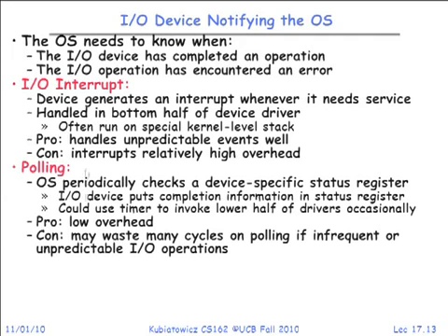What's the downside of polling? It's on my slide, but what does it mean? Yeah, the problem is if you've got an unpredictable device, you're wasting all this time. Are you done yet? Are you done yet? And so interrupts are great for unpredictable behavior because you're not wasting a lot of polling time, right? The lowest overhead thing, when done enough, is high overhead. There's a deep, profound thing that you should come away from today's class with.